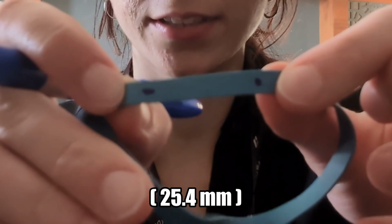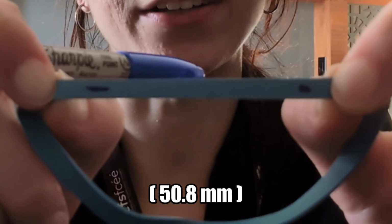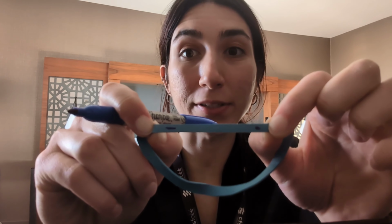Now, if you mark two dots on the rubber band about an inch apart, and you stretch the rubber band so the dots are about 2 inches apart, the rubber band or material has experienced 100% strain. It has doubled its length. Strain measurement is just tracking how much a material stretches compared to its original length.